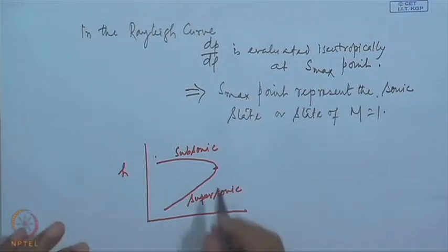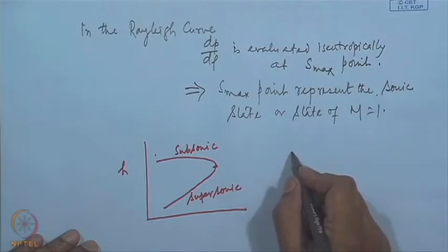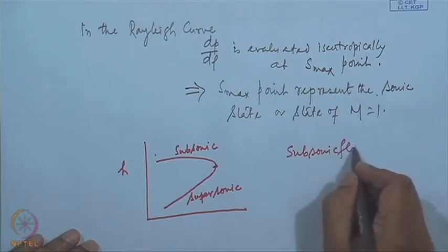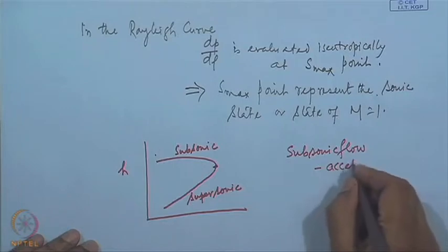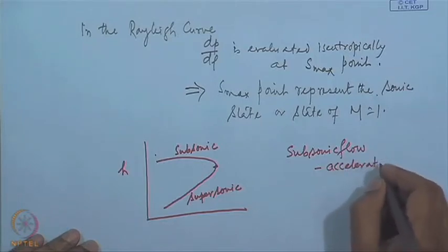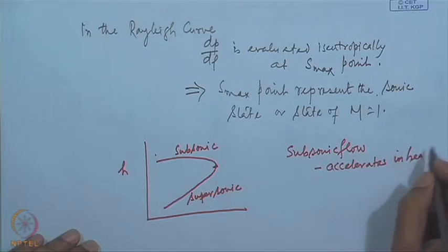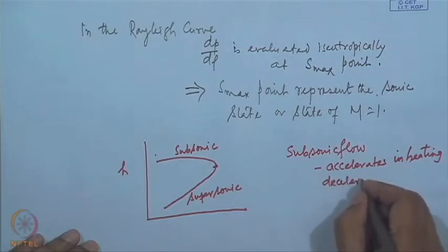From this you can say that a subsonic flow accelerates in heating while it decelerates in cooling.